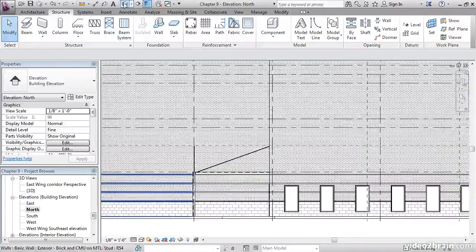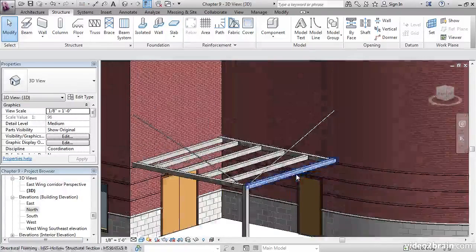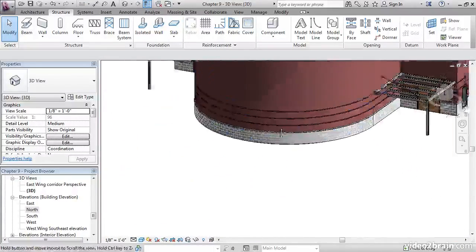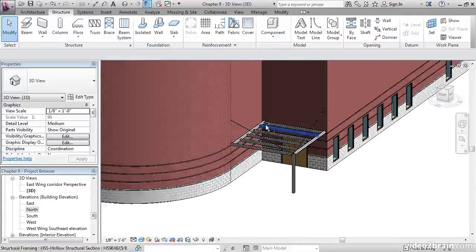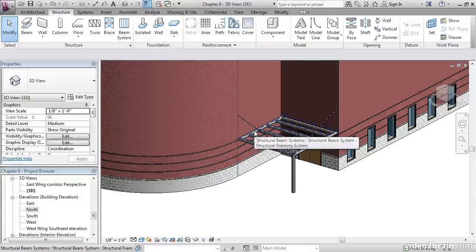Let's go to a 3D view, check it out. Notice the only thing we're going to a 3D view for is just to check it out. Great use of our views, great use of 3D. So if you think about bracing and how it interacts with the actual columns and the grid lines, we were able to use everything we've been adding to our model. Framing, grid lines, elevations, and reference planes all contributed to a pretty easy task. The more you get in the model, you'll find the easier it is to model.